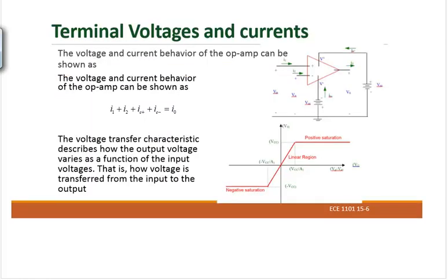When you look at the operational amplifier circuit, current goes from the sources, current goes from the inputs, and current goes out at the output. But again, when you add them together, it will be equal to 0. That makes sense because of KCL. But I1 and I2, or IP and IN, will be equal to 0, because the open input means there is no current going inside. We're gonna look at this equation one more time later. That's why we can use KCL.